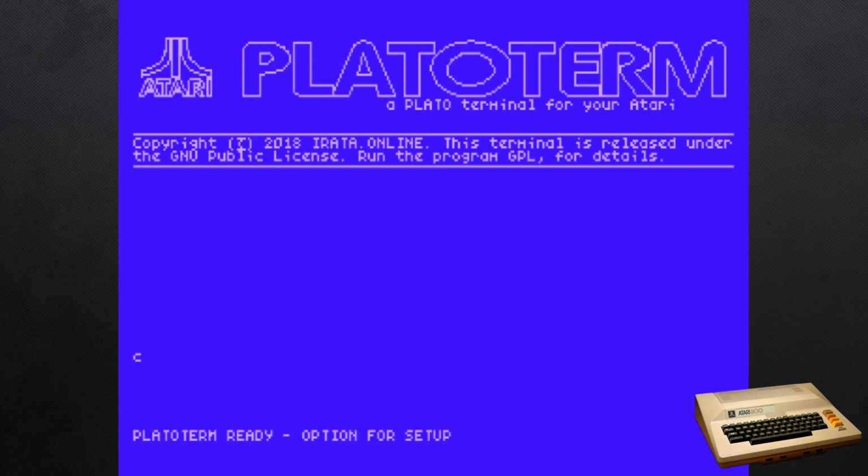We can see that the serial port is working because we got indication that the driver was loaded and initialized, but also something I left in for the purposes of debugging. There's an echo packet that's stuffed inside of the splash screen, and we see the result of that echo packet out here as a C. I just left that in so that I could make sure that the serial port actually works. And if we type, we can see that we get an OK back.